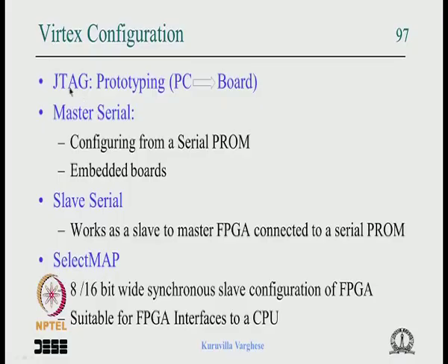So the PCB gets fabricated and chips get mounted on it, and boundary scan is a test port that came for the continuity check through the boundary of the chip, electrically, not by probing. You can call it a kind of inbuilt probing inside the boundary of the chip through the test access port. So that is used even for FPGA programming. Basically this port is a serial port with a minimum number of lines, so as not to waste pins.